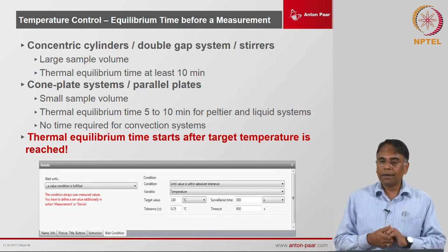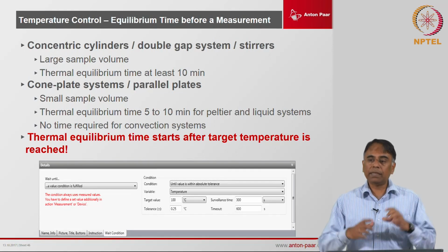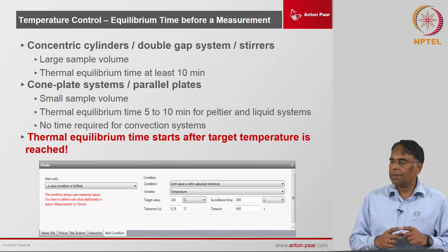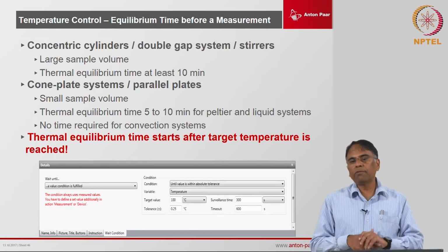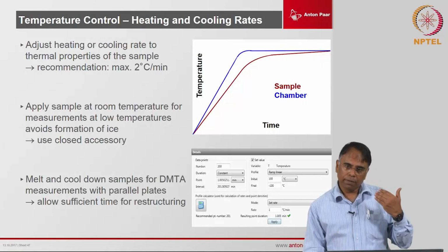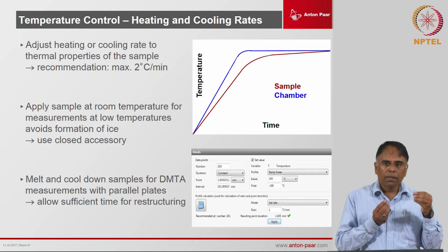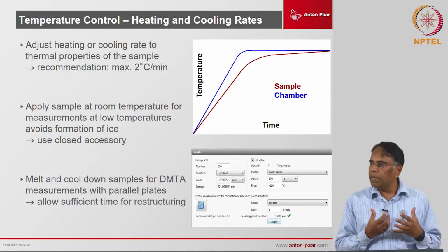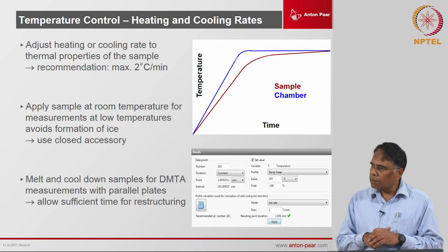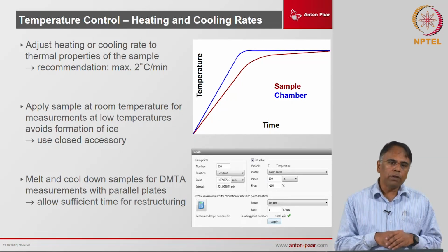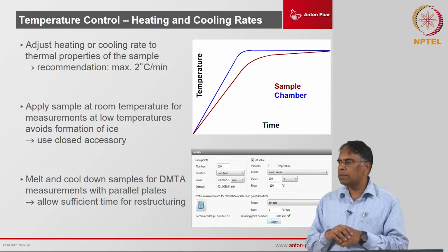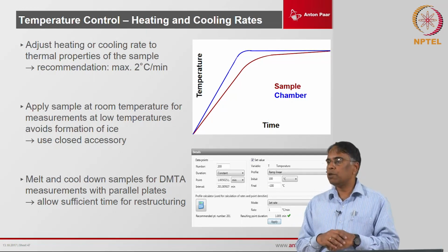If you are doing a measurement with a solid fixture, for example, then the samples are going to be quite big, 50 mm length, 40 mm length, and those will of course take more time. Even though the geometries in those conditions are not very big, the clamps are very small, the samples themselves are quite big, and mostly solid samples, so not flowing also. So, in a static condition, the heating times and cooling times of those samples are going to be also very slow.